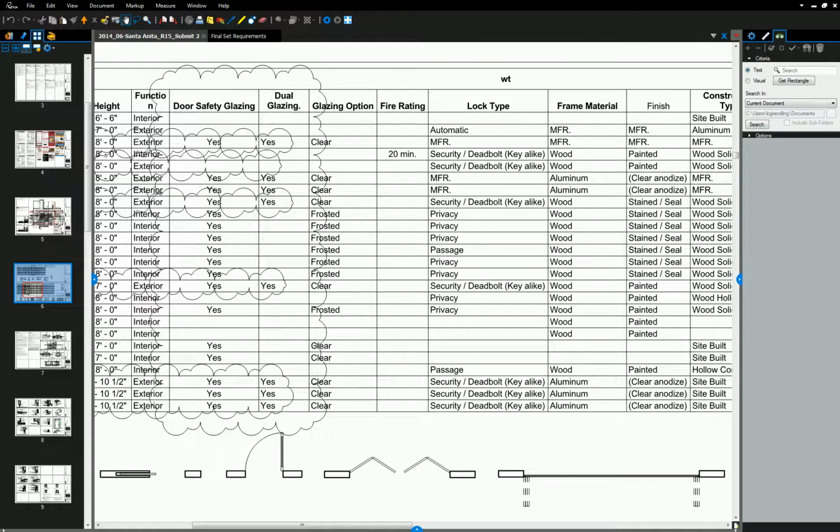So I think that one in particular, guys, if you want to spend time with anything here in class before you take off, this is an important one. Because whether or not you have a project parameter, shared parameter, and whether or not it's type or instance based is kind of critical for this. And it's very confusing. You guys were all very confused when I explained it before.